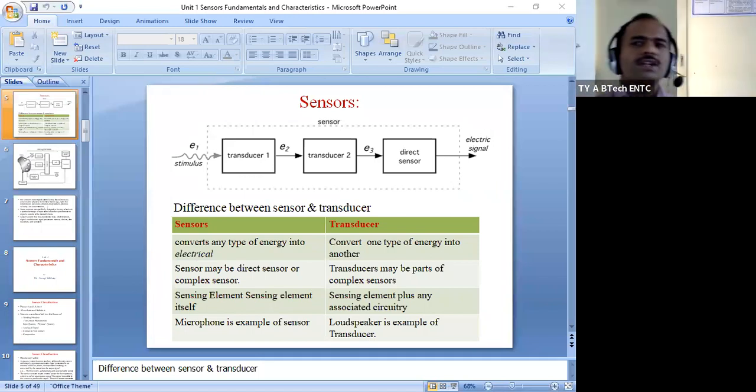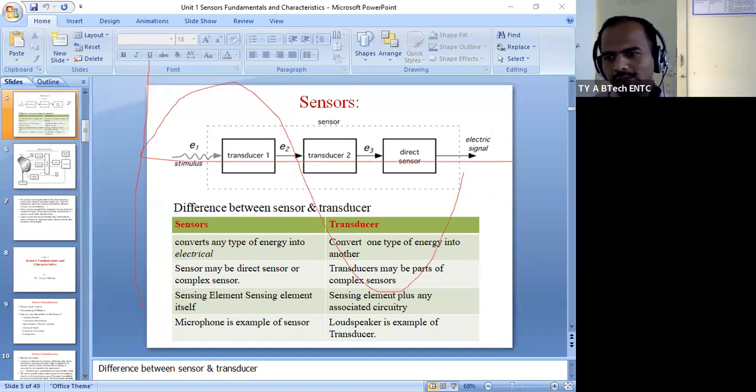Okay, so whenever we are interested in measuring the cycles, that is the frequency of a signal, in that case, these input signals are provided to the comparators, for a specific time interval like 1 second. So in 1 second, how many crests and how many troughs related to a sinusoidal waveform? Suppose this is a sinusoidal waveform like this. So this is the crest, positive, and this is the trough. Positive half cycle, negative half cycle.